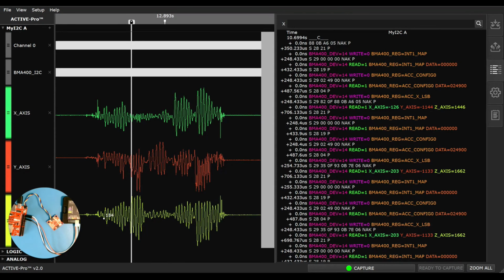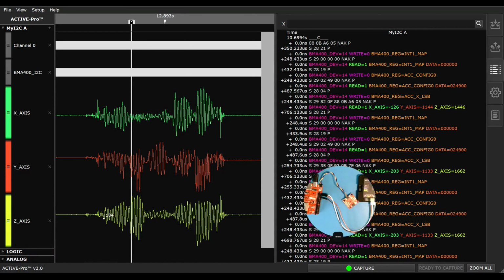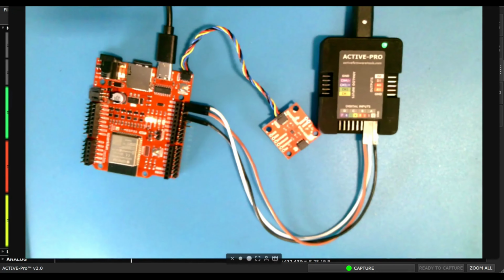Very cool, very helpful. What's even more helpful, however, is doing this from inside the microprocessor, and we're about to show you how to do that. First thing we're going to do is hook up a couple of wires on our board here. We're going to pick 2 pins to send debug data from the ESP32 out to the firmware debugger.